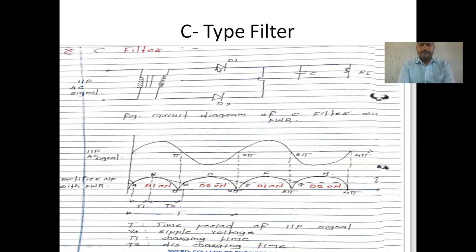Why? See, the reason behind the diode conducting is that the anode has the positive voltage applied, right? So that's why it conducts, right? So the positive half cycle is coming across here. So positive voltage appears across before the capacitor, right? So this will happen during the first positive half cycle.